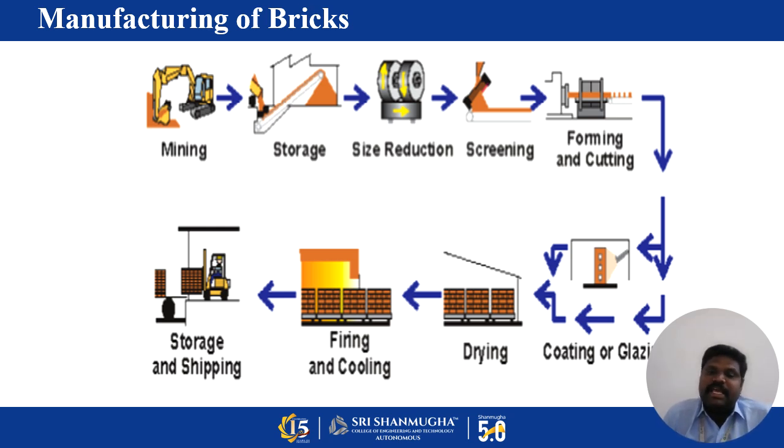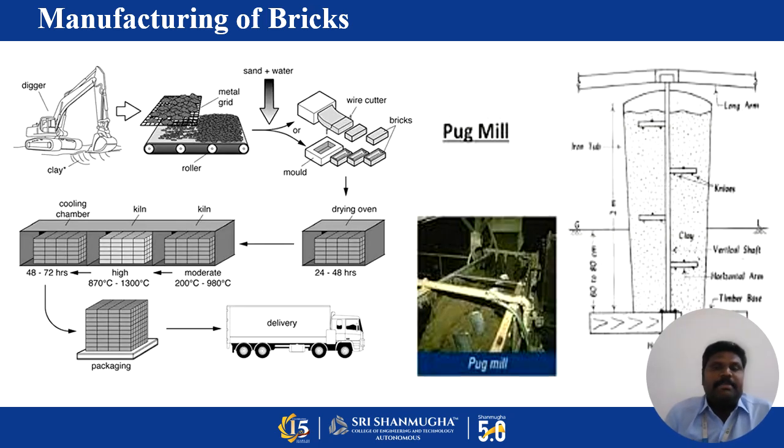So red clay bricks are burnt clay bricks that are used in the market now. These are the manufacturing steps: clay digging, roller, sand and water mixed in a mold, then drying in an oven, moderate and high temperature, and a cooling chamber. Then comes the packaging.